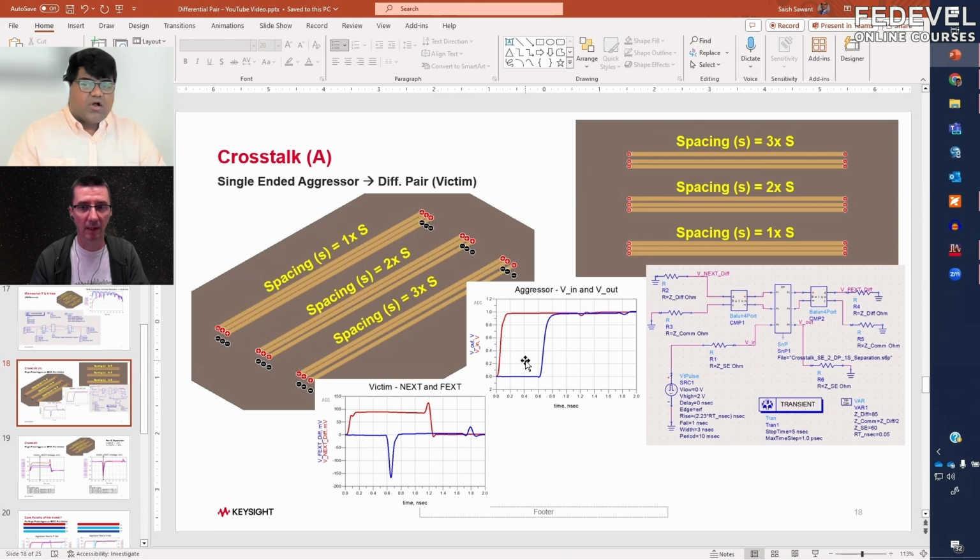Okay, so again, I will interrupt you. Sorry. On the left and on the right, these are the blocks which are changing the single-ended signal to a differential pair signal. Yes, it's called a balun, and you see that there is D and C. D is differential and C is the common signaling mechanism. On the other side of the block, you see plus and minus.